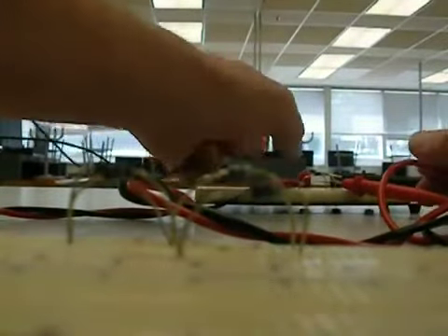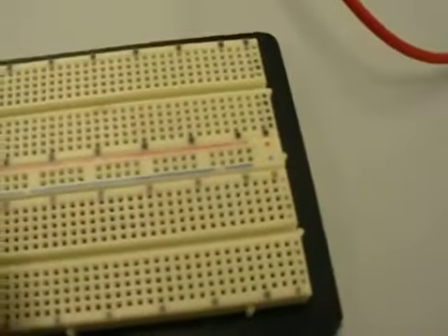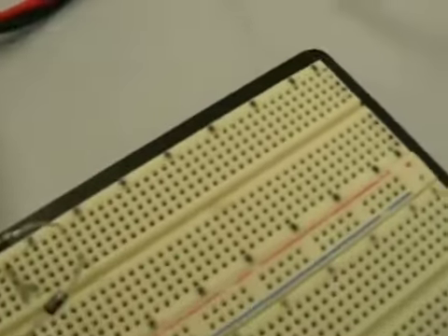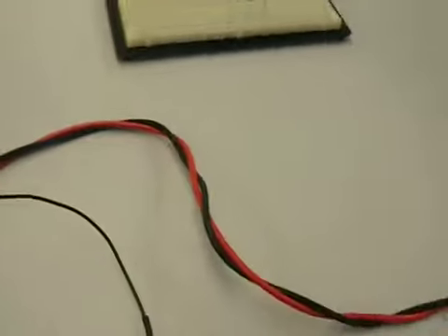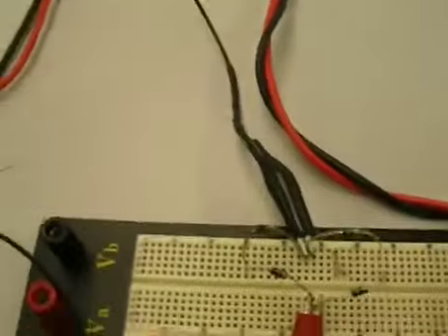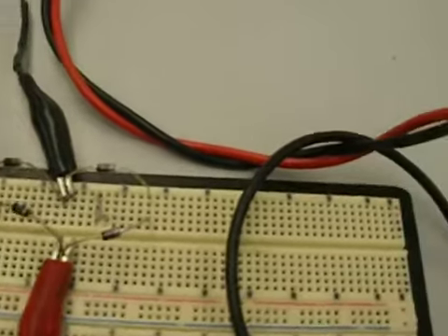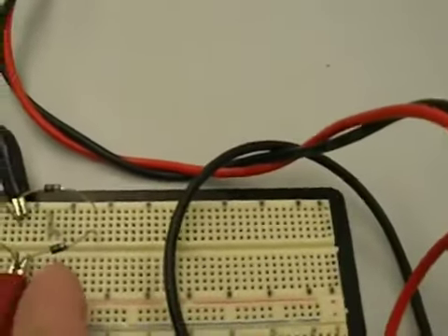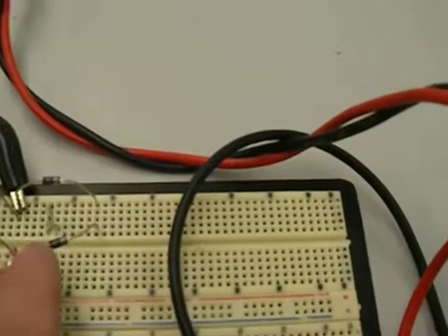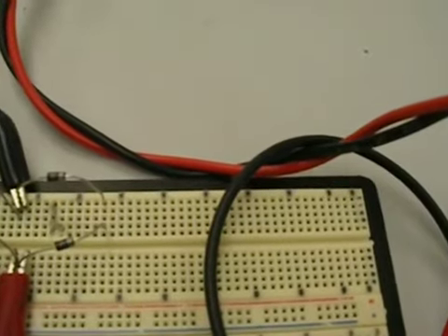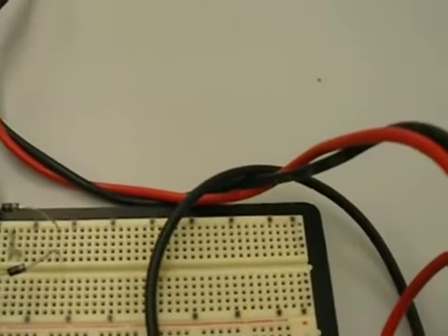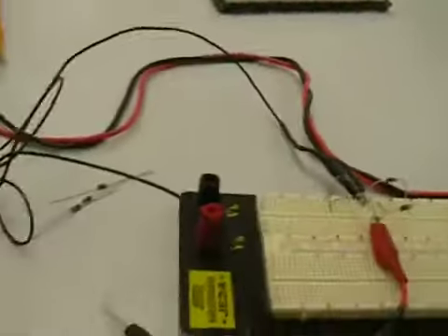So how do we hook up the voltage to it? Well, the power adapter actually hooks here in the middle. So we put one on one side, one on the other, and now we have the voltage going in. For reading the voltage coming out, remember, when AC is converted to DC, if it's hooked to the positive end of the diode, you'll get positive voltage on the negative end. If it's hooked to the negative end, like here, then you get negative voltage on the positive end. So this is where I'll get negative voltage readings. Here's where I get positive voltage readings.